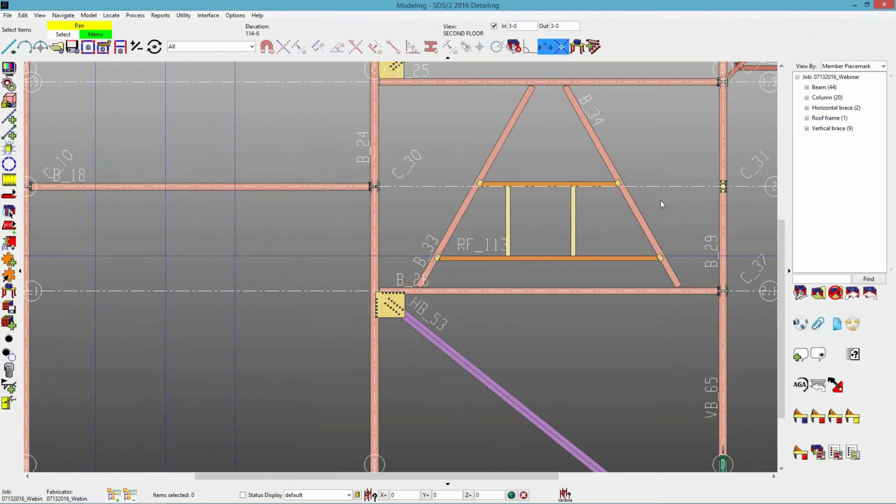And we could import this into our part library, and then we can add that as material or members in any of our models so that we get that information more accurate in your model. You'll get that information then transferred over into your bill of material and different things like that. So like I said, just a good place to organize different buyout items or anything else that you could import using a DWG, DGN, or IFC file.